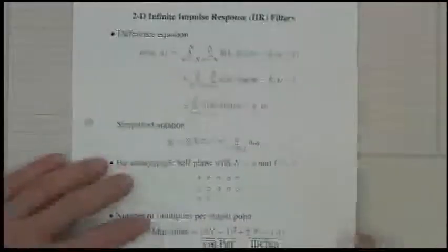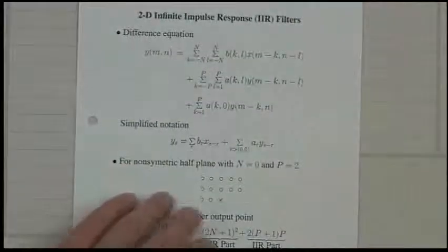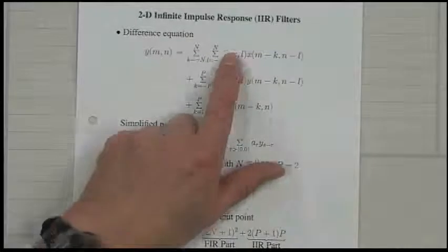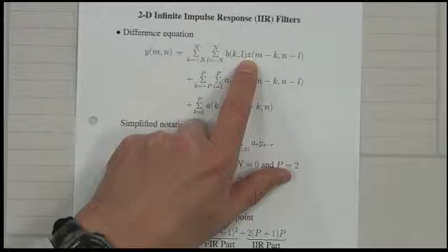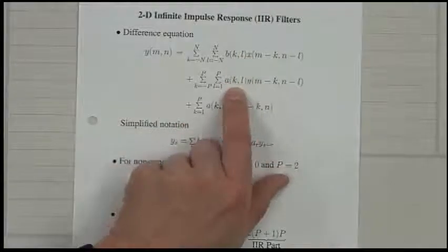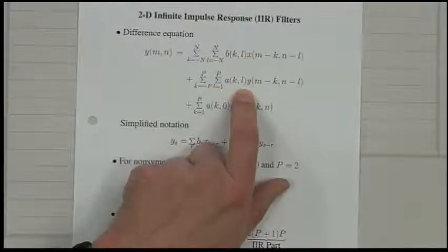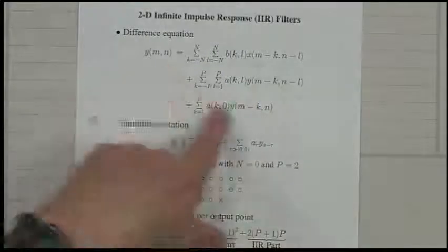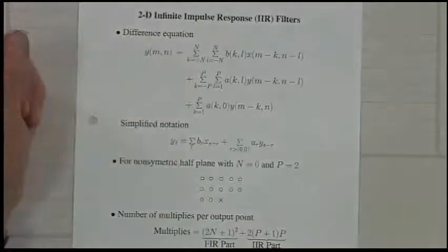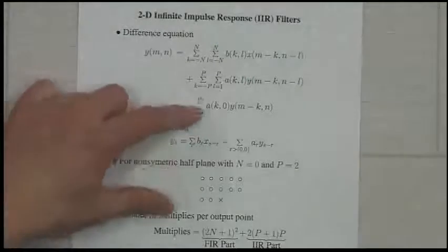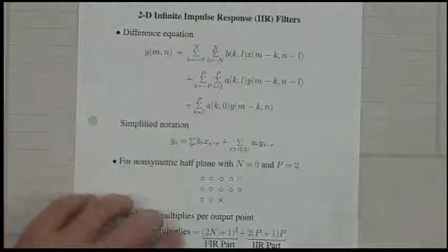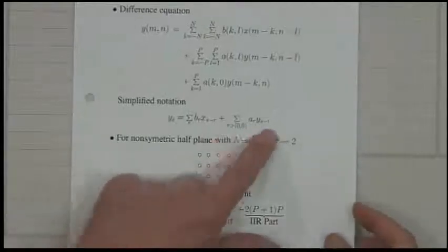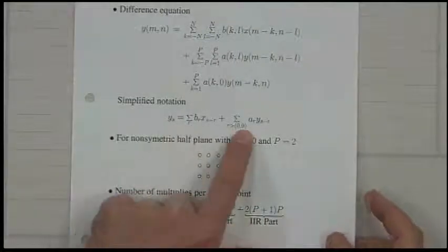So in that context, an IIR filter can use a window of points of input, and then it can only use previous output points to calculate the current one, because otherwise they're not available yet, right? So the coefficients are the A's and the B's, and if you calculate the impulse response, you can write it more compactly like this.